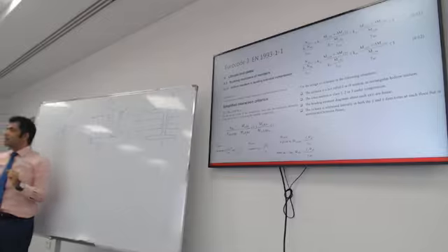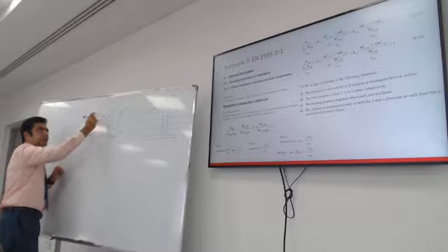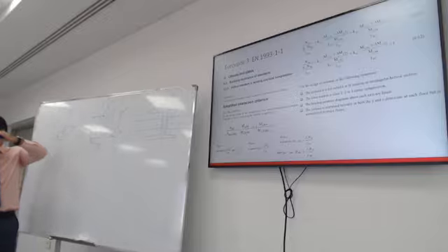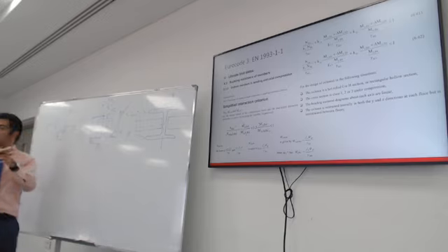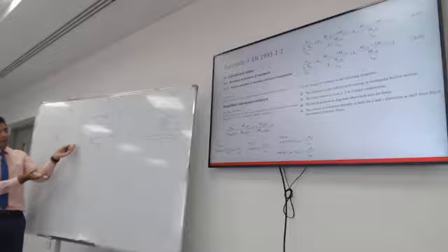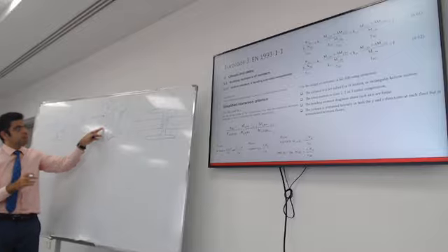So you will find that moment about x and moment about y and axial load, you add up all these stresses, and that will be like the worst case scenario. That corner is resisting moment about x and moment about y and the axial load. The opposite tip or corner is feeling the tension side of the moment, so it's not as critical. Having said that, you need to make sure that the material is not going to fail anywhere.